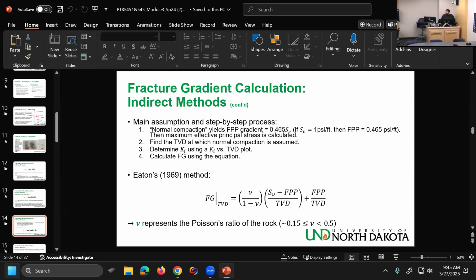This is bad. This is not how you do science, okay? If the machine gave you 0.7, there is a reason why it gave you 0.7. It doesn't mean that it's a Poisson's ratio of 0.7. It was reading 0.7, an apparent value, maybe because of something related to the material. The way the material was behaving made the machine think that it's 0.7, okay? Multiple layers, one pushing on the other. It was a synthetic sample, something like that. But it doesn't mean that the material had a Poisson's ratio of 0.7, okay?